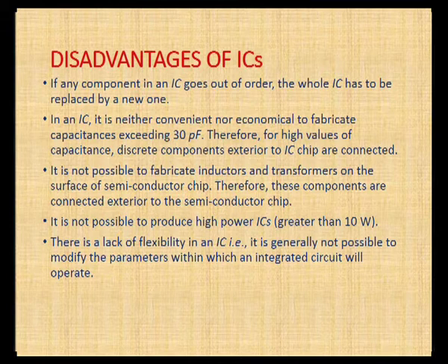If the capacitance exceeds 30 picofarad, the IC's fabrication is not economical. Therefore, for high values of capacitance, discrete components are used exterior to the IC and interconnected together.